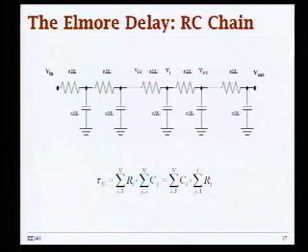And then we introduced this simple delay model based on Mr. Elmore, who made this nice observation that your wire delay can be expressed simply by going through each of the nodes in the network and observing what are the equivalent resistances and capacitances that are contributing to the overall time constant.